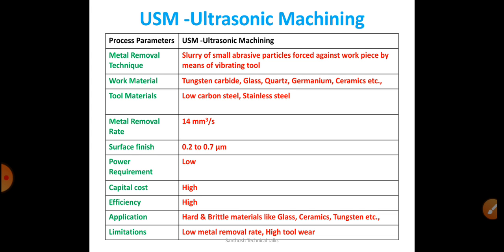Metal removal rate is 14 cubic millimeters per second, and surface finish is 0.2 to 0.7 micrometers. Power requirement is low, capital cost is high, efficiency is high.